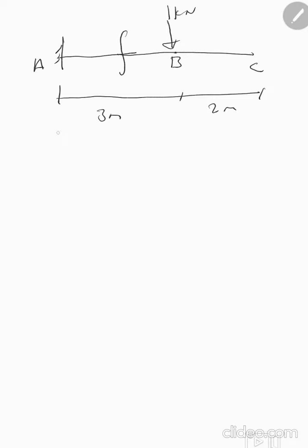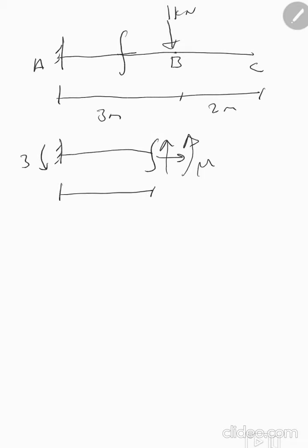So the drawing will be like this. Here we have a horizontal force, a vertical force, and a moment, and here we have the 3. The 3 is the value of the moment from the previous page. And this distance, I cut it at some point whose distance I don't know exactly, so I will make it X.